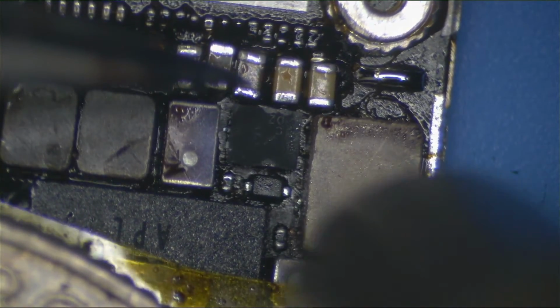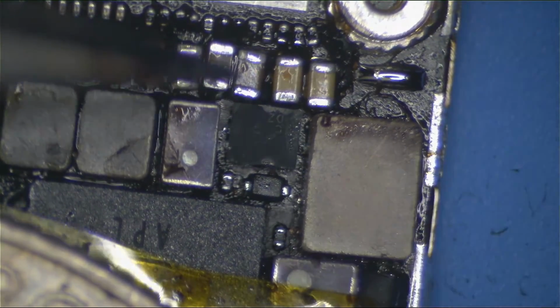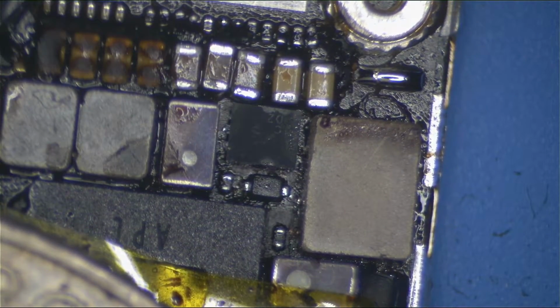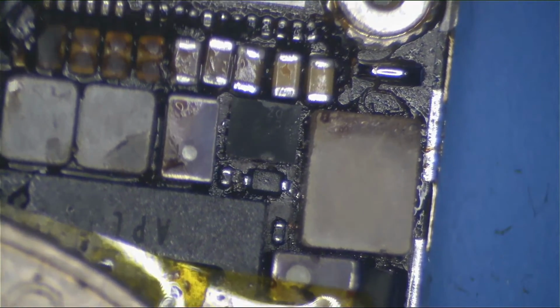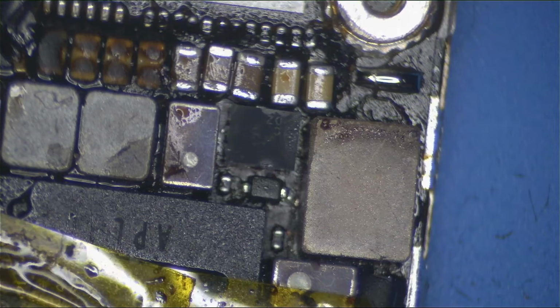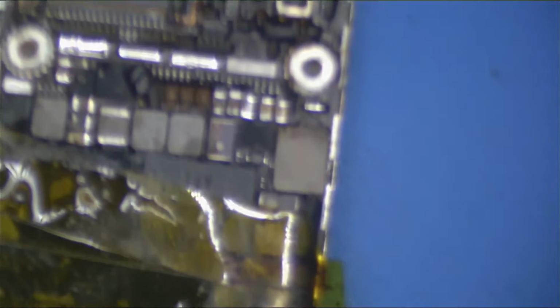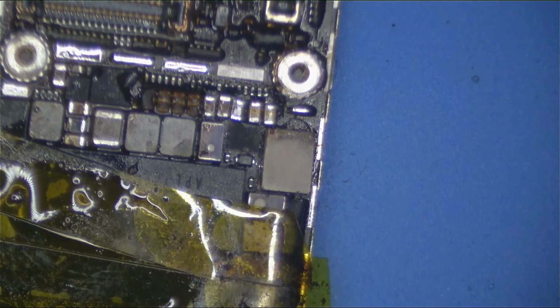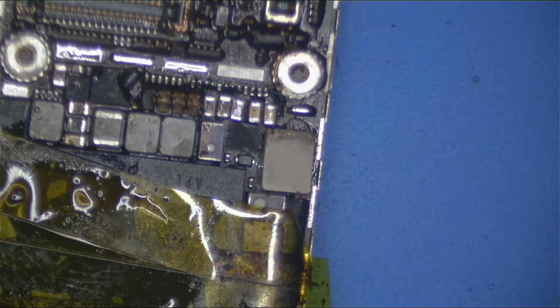Yep, there's one corner. Oh yeah, perfect. Look at that, beautiful. See, that's perfectly parallel with the diode there. So that's a good solder joint. Yeah, there you go. And zoom out, just look. So what you want to do is look for solder balls that are popping out of the underfill. That's what I'm doing here. I'm just zooming out, making sure everything looks okay.